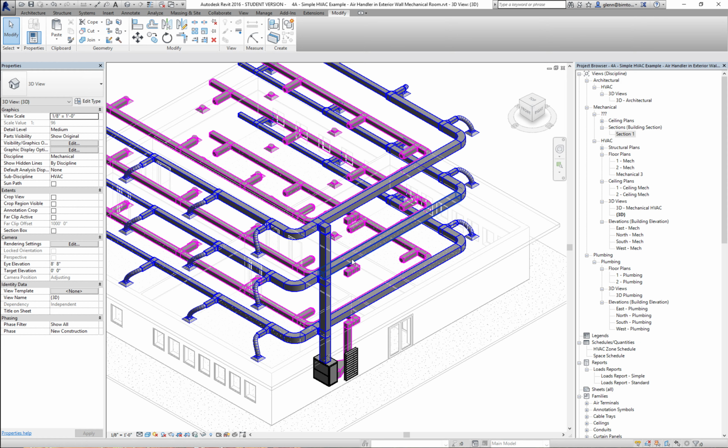Just to add a note of reality to all this, as we size the ducts, things are going to keep on getting bigger as you go all the way down. If this size is big enough for one floor, you can imagine twice the volume on the second floor, then 3 times the volume down on the third floor, as it's all chaining in there. So if I size the whole system, the ducts get bigger and bigger as they come back towards there, and you'd probably need a bigger air handler down there at some point. But at a high level, that's what it's doing. That kind of makes sense. I'm checking with you.